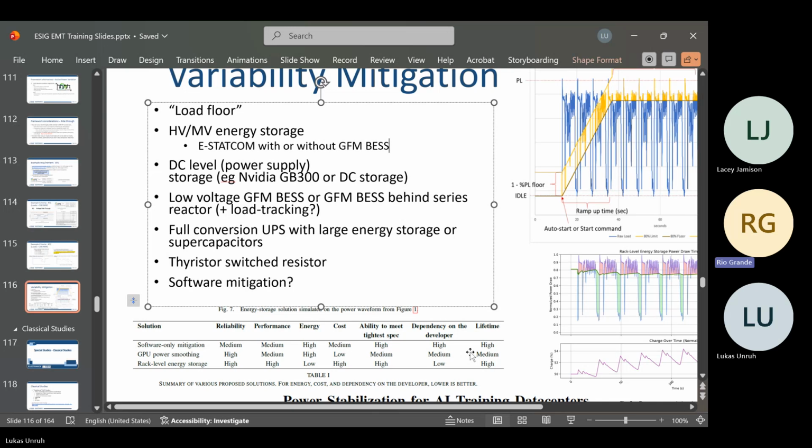And the eStatCom, what they're proposing would be to measure the load fluctuations, feed that measurement into the controller, and then just offset it all the time so that you get a balanced load profile when you look in from wherever it's connected. So this is typically a measurement-based solution here, and how effective it's going to be is just a matter of how fast the fluctuations are.